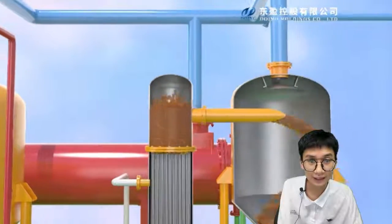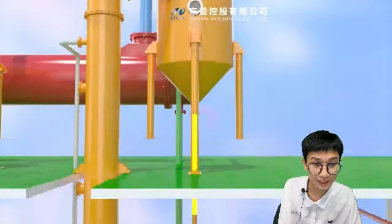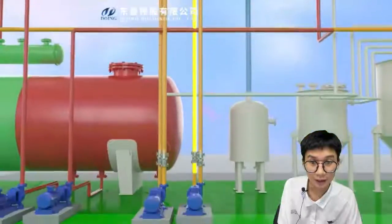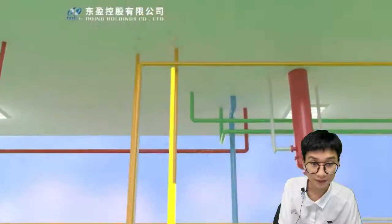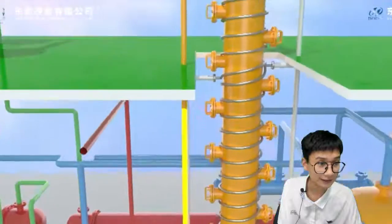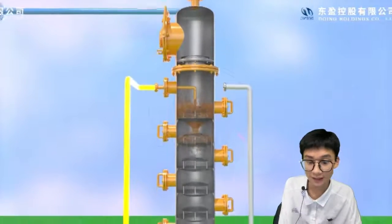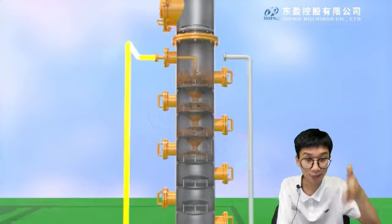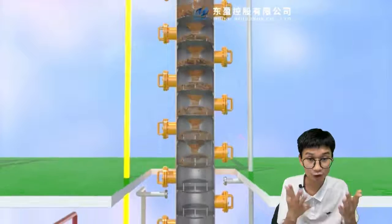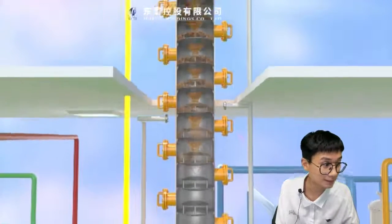While the evaporation system is working, the mixed oil is taken from the tower top inlet pipe, first loading onto the overflow tray of the first unit tray. Let me just make it simple. All of the micella will drop from top to bottom, and the heat comes from bottom to top to fully evaporate the hexane out of the micella.